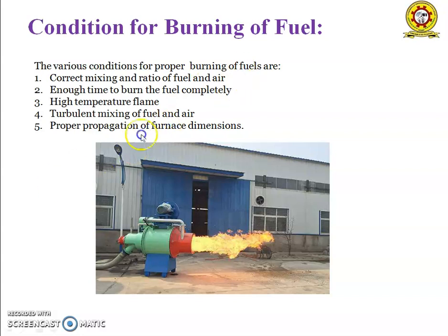This is the burner. Burners are used to burn the pulverized coal. The main difference between the various burners lies in the rapidity of air-fuel mixing, that is, turbulence. For bituminous coal, the turbulent type of burner is used, whereas for low volatile coals, the burners with low flame or long flame should be used.